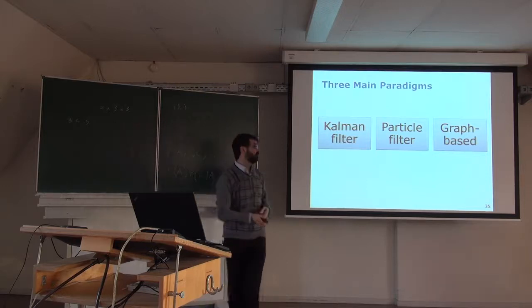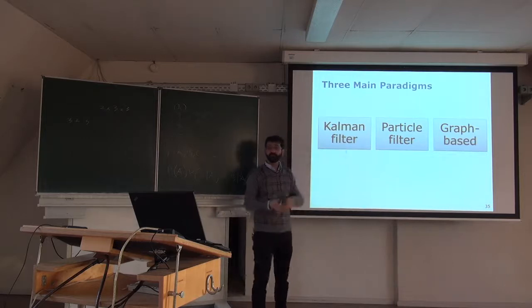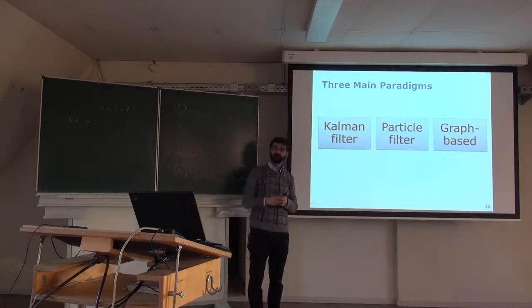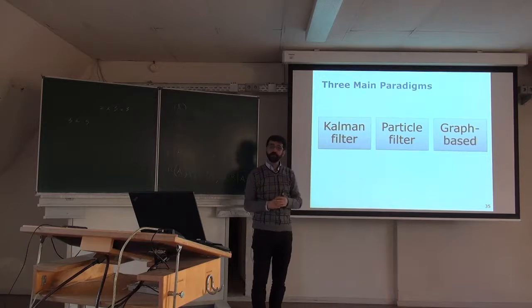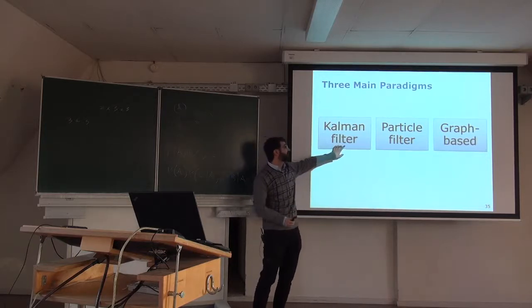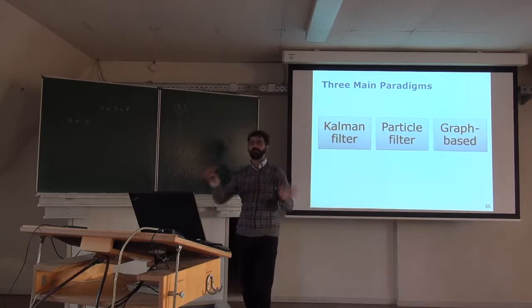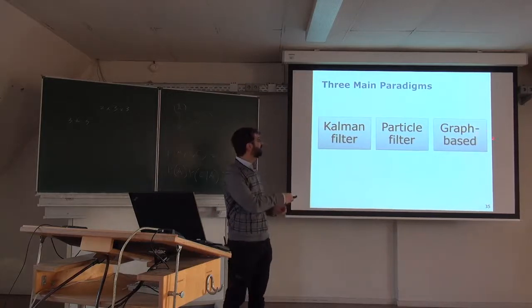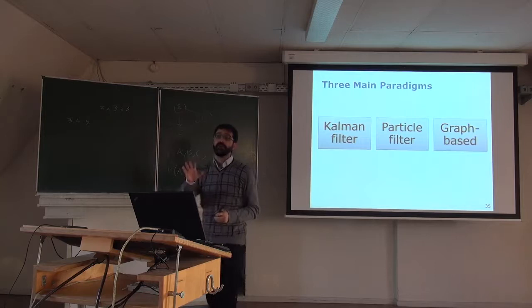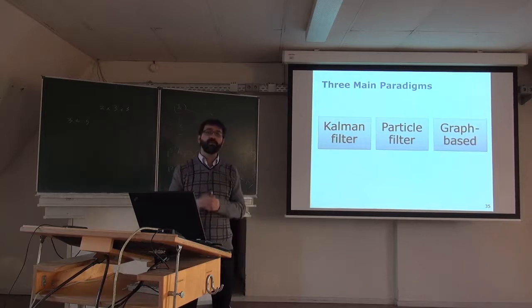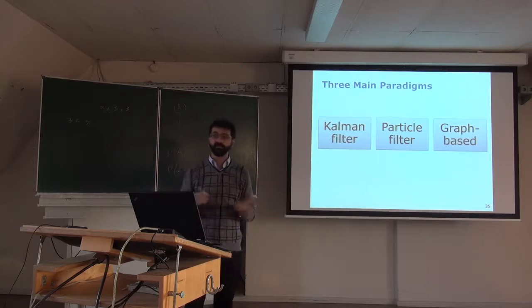This is something that also happens in the Kalman filter through the correlation that I've shown you before, because everything is correlated. But if we have a nonlinear system, as we have, the things are not exactly the same. So you can find, under certain assumptions, that the full batch optimization and the incremental optimization give you the same result. But unfortunately, these assumptions do not hold for a real world with a real robot. So you can talk about them theoretically, but in practice, they do not hold.